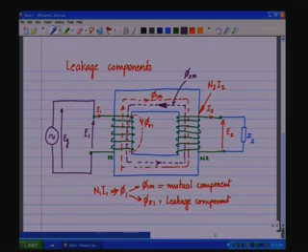But this also produces some ampere turns which push some flux through the air here, and it has a path something like that, and this is called phi sigma 2, and this is the leakage component of the flux due to N2 I2 ampere turns, and this phi sigma 2 does not link with the primary, only phi 2 m links with the primary.